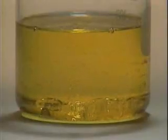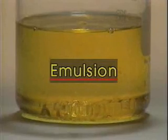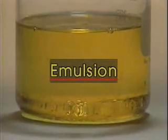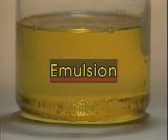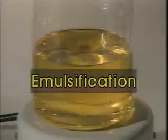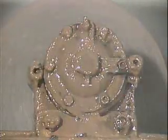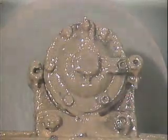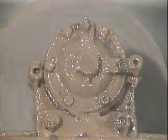A lubricant's resistance to forming an emulsion is also important. Basically, an emulsion is a mixture or suspension of components that are difficult to separate once they've been combined. The process that causes the formation of an emulsion is called emulsification. A lubricant that resists forming an emulsion is usually desirable because an emulsion of lubricant and water has poor lubricating qualities.